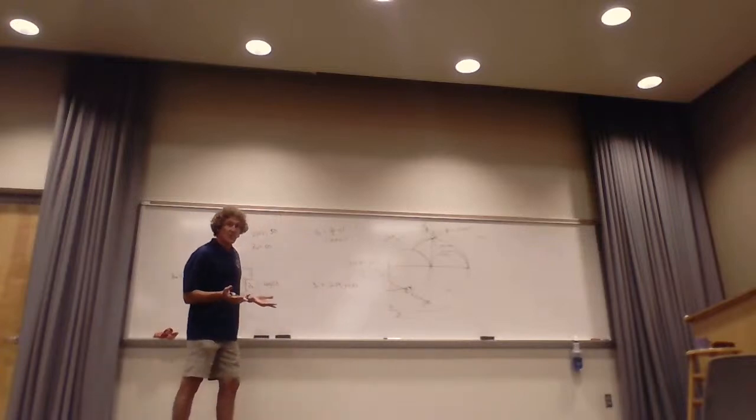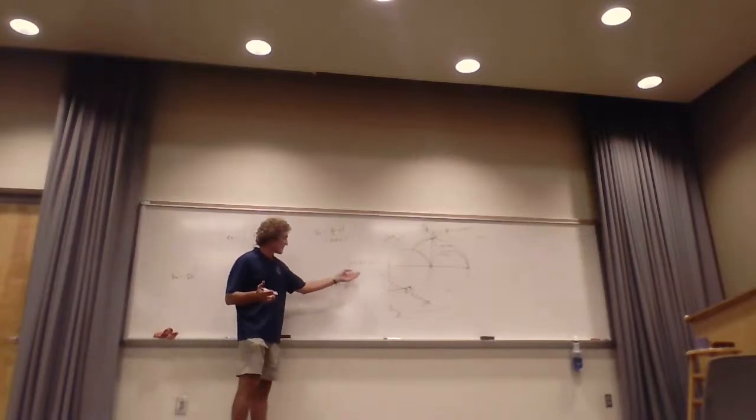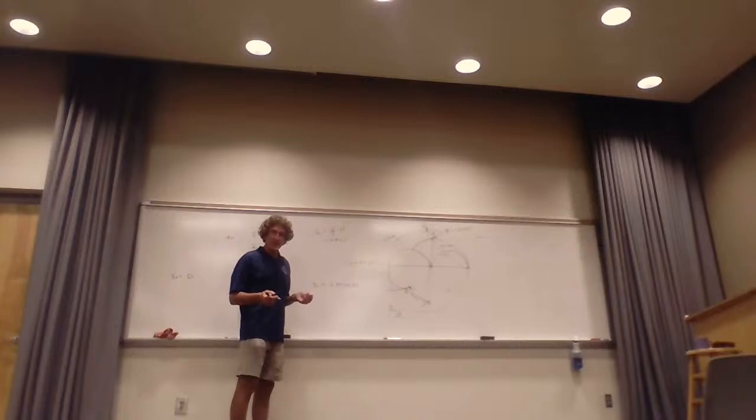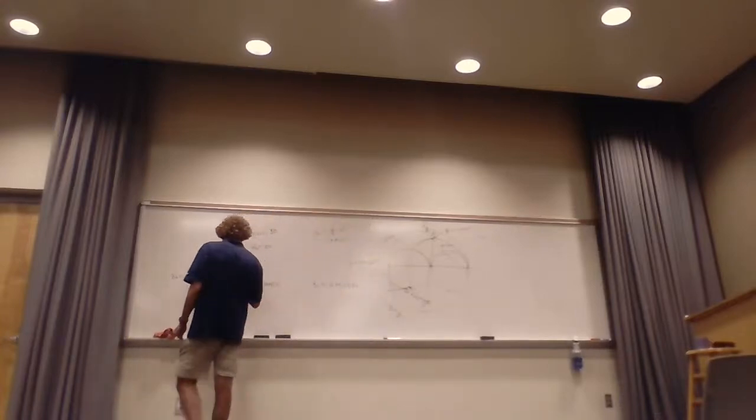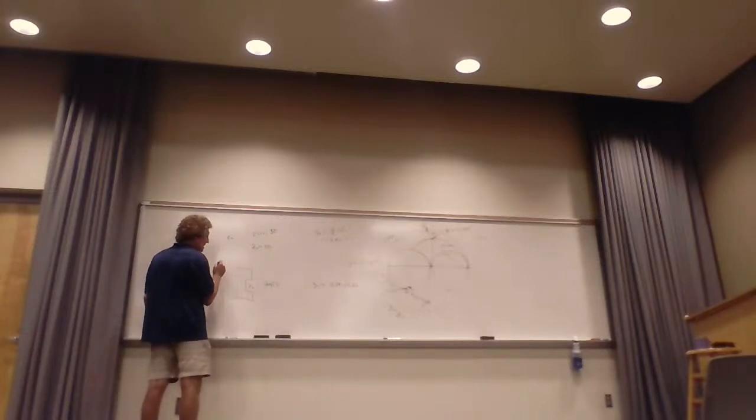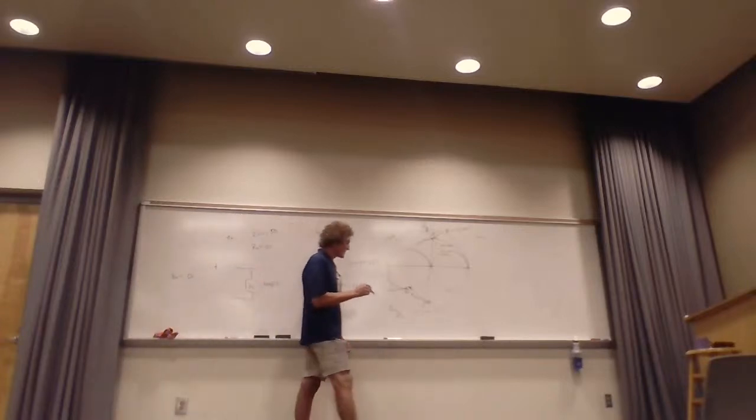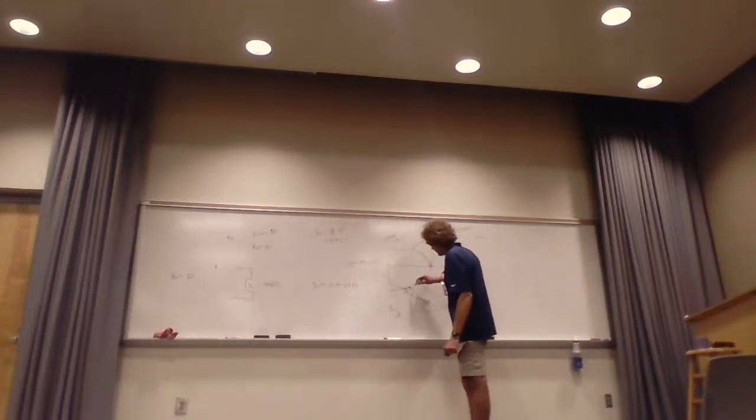Now, the nice part is this. I've got to see how much I've added to get to there, right? So if I just take 0.86 and subtract 0.5 from it, 86 minus 50, that's 0.34, isn't it? Right, so it's J 0.34. So I added in series for this one, this is going to be normalized, a J. You know what though, if I want an inductor, I don't want to end up there. I want to end up here.